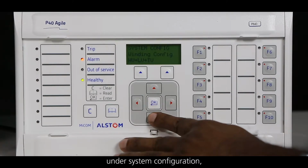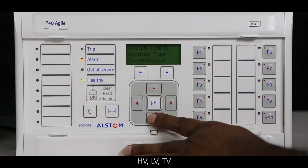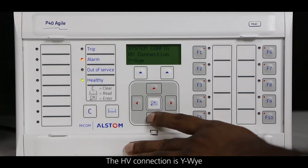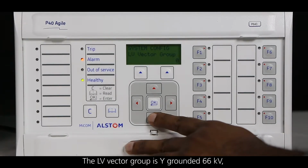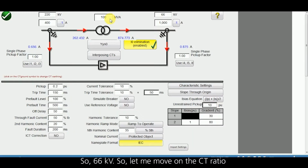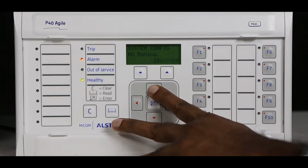Under system configuration, I will be able to get the transformer's winding details: HV, LV, TV. The HV connection is YY, 220 kV, 100 MVA. So it is matching here, 220 kV, 100 MVA. The LV vector group is Y, grounded, 66 kV. So 66 kV. Now let me move on to the CT ratio.